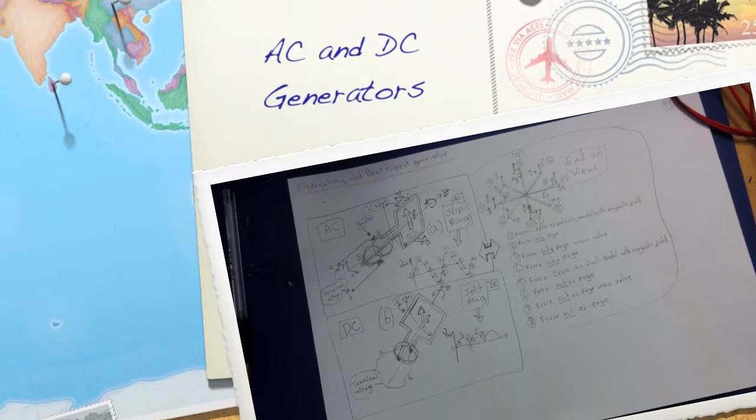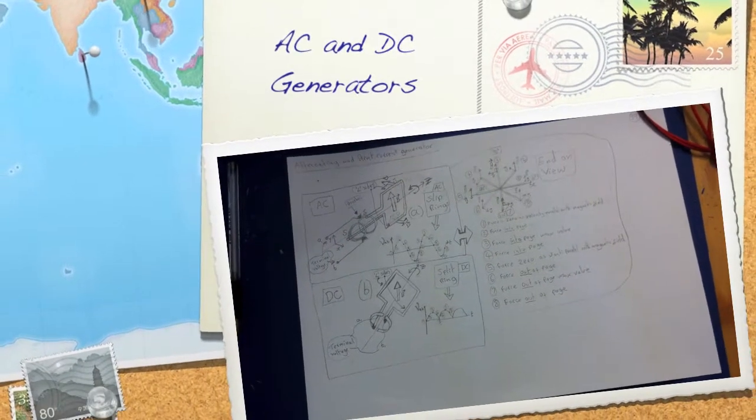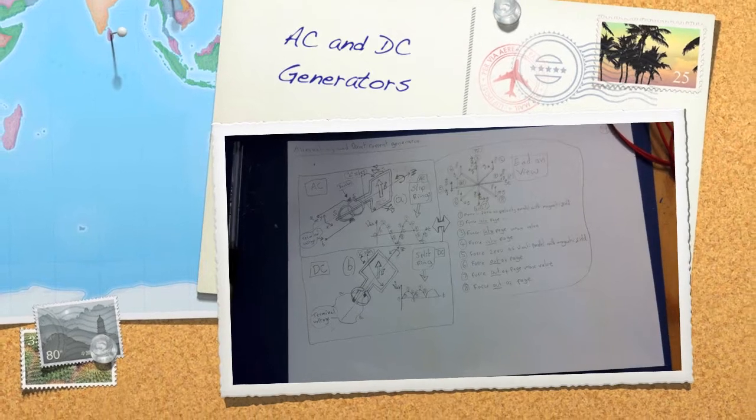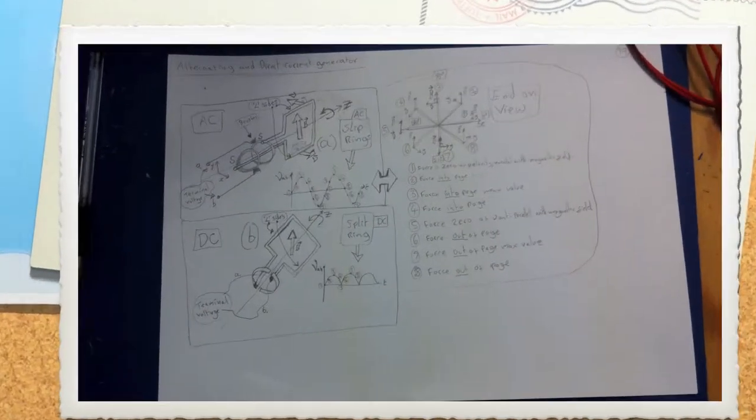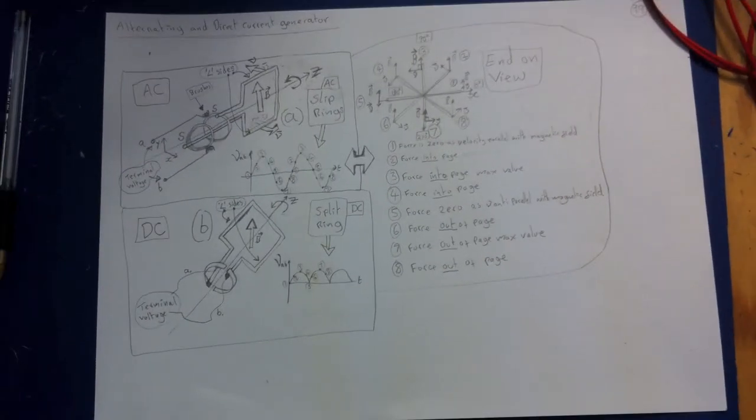The rotating loop is the prototype of one type of alternating current generator, or alternator. It develops the sinusoidal varying EMF. The EMF is maximum in absolute value when theta equals 90 or 270, and the long sides are moving at right angles to the field.